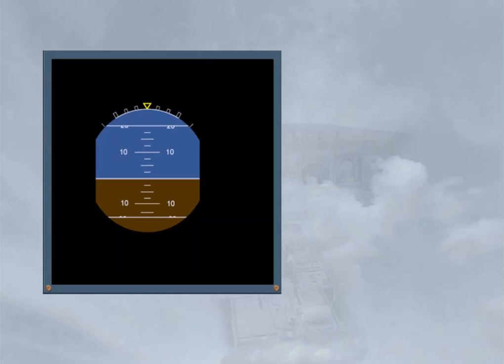The attitude indicator works in the normal sense. The pitch scale has white markers, as shown. Beyond 30 degrees, large red arrowheads show the direction to move the nose in order to reduce the pitch. The roll scale is displayed at the top of the indicator. The yellow triangle shows the 0 and the white markers indicate 10, 20, 30 and 45 degrees of bank. The aircraft is represented by a fixed symbol, in black and outlined in yellow. Note, if V-bar's option is installed, the aircraft symbol is as shown.